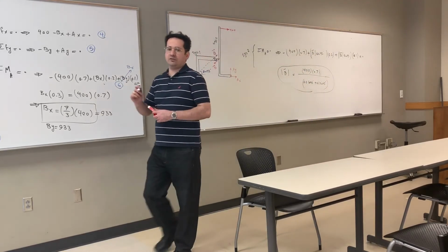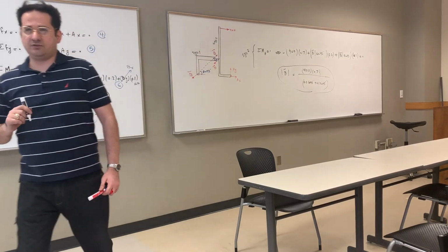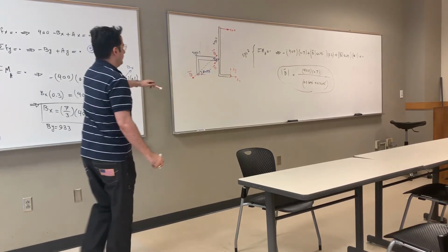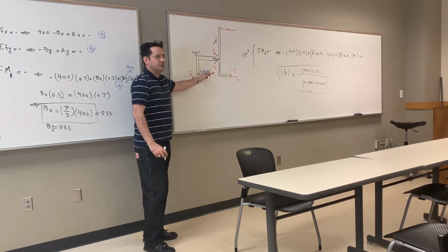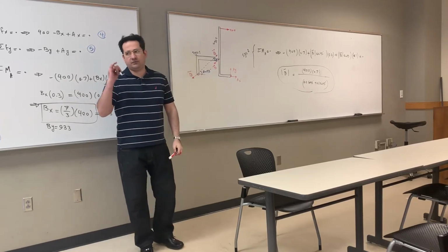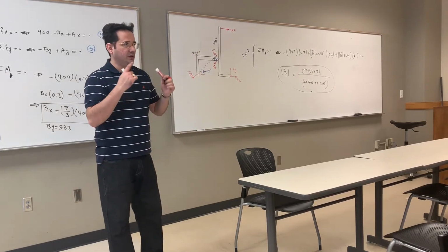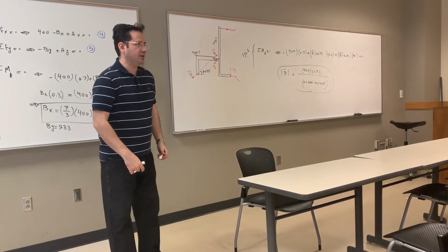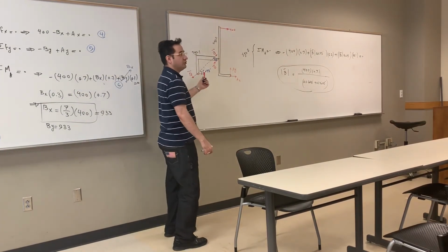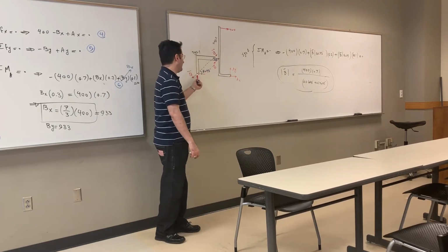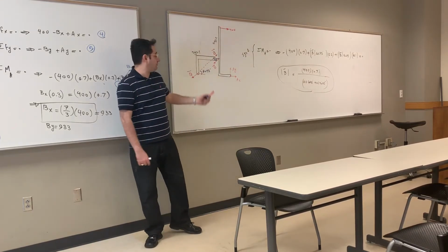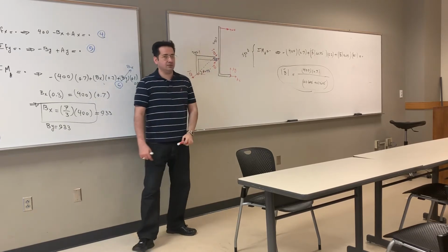You see, you could solve it with one line, just starting from scratch, as long as you know this concept, the two-force member. A member that only has two forces at the ends. If it's massless and frictionless, you only have one single force that is equal and opposite at the two ends. You don't have the value, but you have the direction, along the line connecting the two ends together. It doesn't matter what shape you connect it as. Okay?